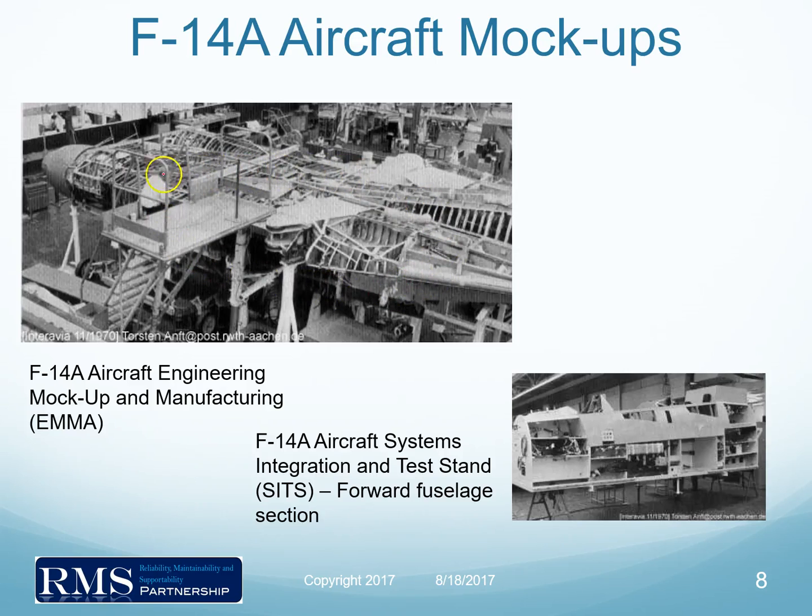Here, this is a mock-up of the whole aircraft, the aircraft engineering mock-up and manufacturing, called the EMA. These are for the A, but for the D version, which is what I worked on, we did the same things. And here you make a mock-up to test out all sorts of things. You want to make sure that you have the right kind of cabling length and cabling type and location of cabling that runs through the aircraft. You want to make sure that you have boxes in the right place and structural integrity, and you might take out sections and put them in a wind tunnel, once they were actually covered, and things like that.